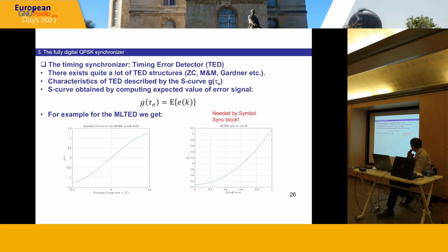And you will get, in fact, if you look at the graph on the right, a gain of this timing error detector, which is the KP we saw just before. It's the gain of your TED that you have to put into the block. So the problem is that a MATLAB script was given to determine by simulation these different KPs, but not for RRC pulses.